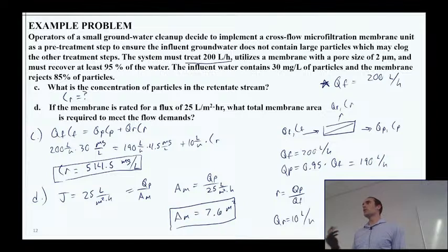Okay, and you can imagine we could solve problems with membrane resistance and flux and pressure. It's not going to be a huge amount different, and we could then relate, given some flux that we calculated, what membrane area do we need? Do we need some new membrane area if the resistance increases a certain amount? We can connect a few more pieces there too, but it's not inherently going to be that much different than what we're doing here.